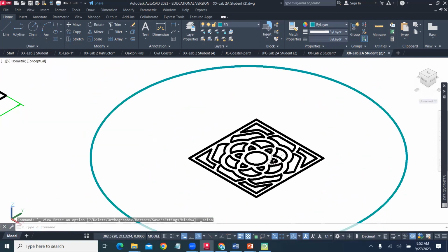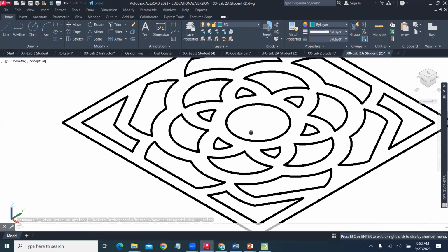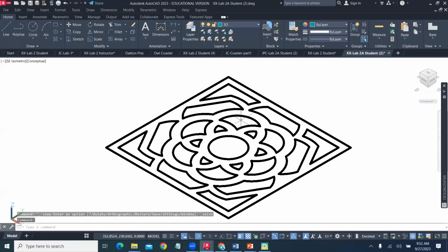And then the part has already been drawn two-dimensionally. And as we look at the part, we want to look at how it's going to be created. And so when we create things or we design for 3D printing, we want everything to be connected. We don't want a piece to be unconnected. And then when we print it, it won't hold together.